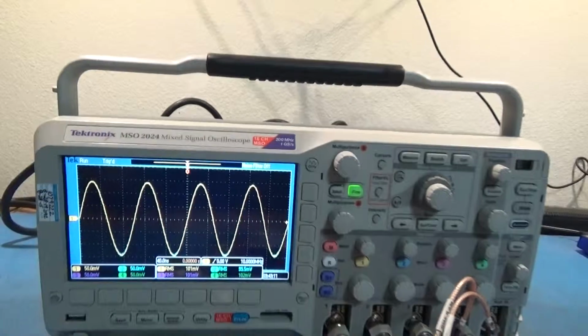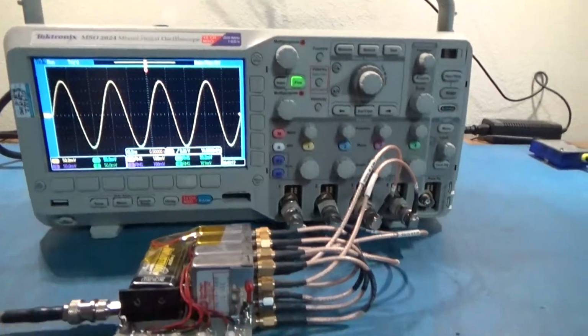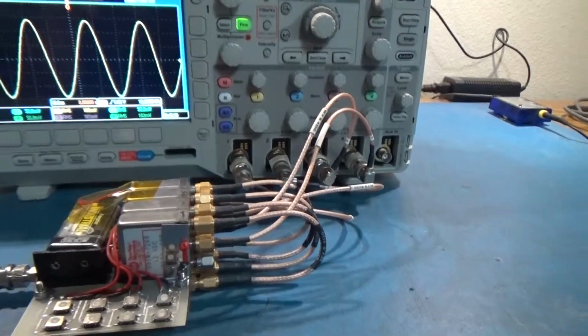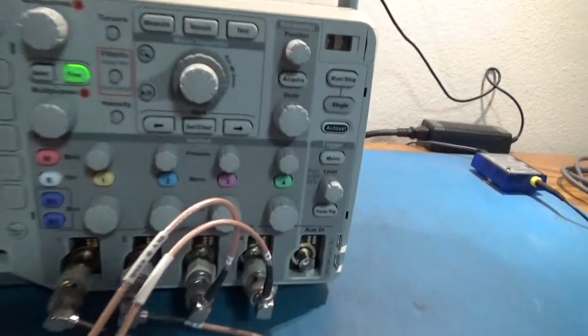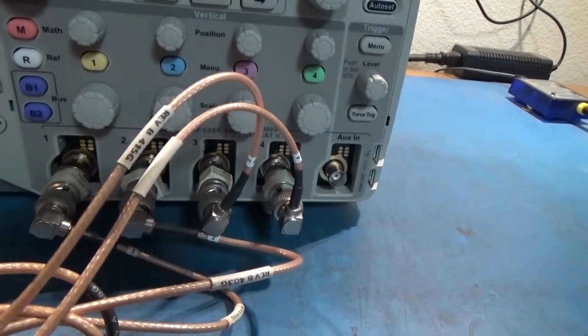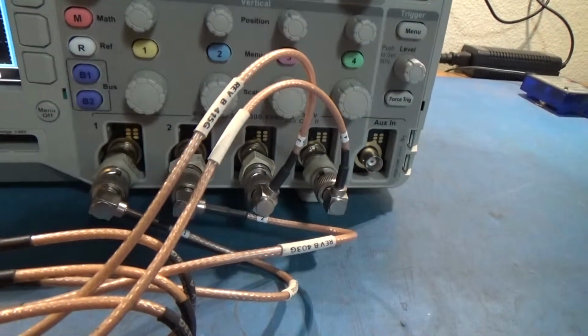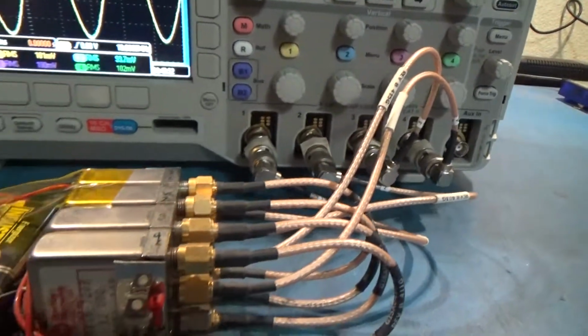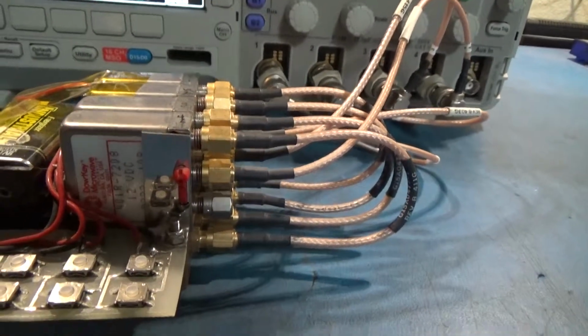So anyhow, what I have going on is a signal generator over here, putting out a 50 ohm signal to a 4-way power divider, and 50 ohm terminations on the inputs to the scope, because the scope can't provide those kinds of terminations, and the relays there are good out to about 18 gigahertz.